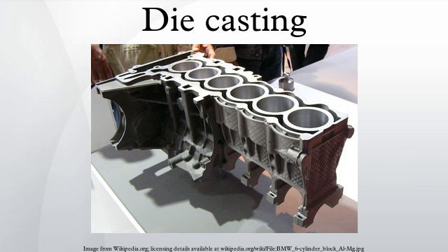The high-pressure injection leads to a quick fill of the die, which is required so the entire cavity fills before any part of the casting solidifies. In this way, discontinuities are avoided, even if the shape requires difficult-to-fill thin sections. This creates the problem of air entrapment, because when the mold is filled quickly there is little time for the air to escape. This problem is minimized by including vents along the parting lines. However, even in a highly refined process there will still be some porosity in the center of the casting.